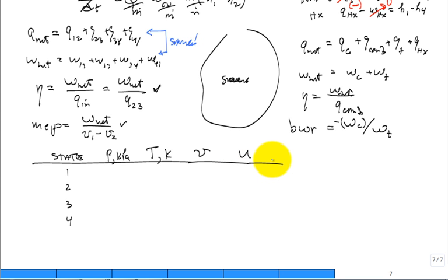It's always an ideal gas. And the way the Otto and the diesel cycle problems go is that this pressure and temperature often are given. And so you can calculate V1. V1 is equal to RT1 divided by P1, isn't it? Just using the ideal gas equation.